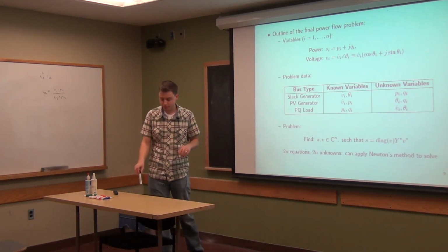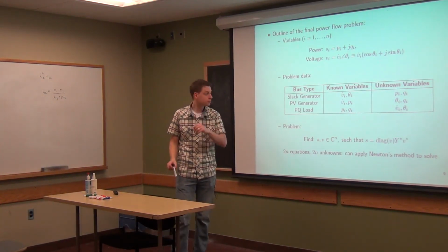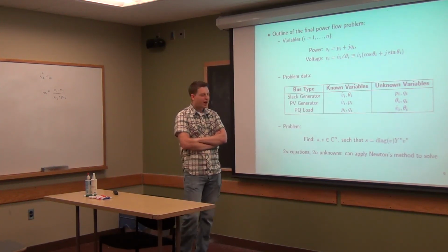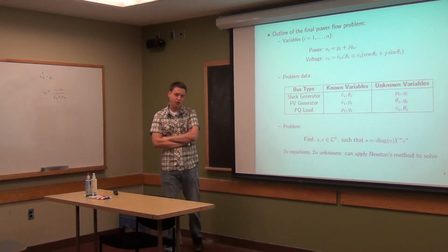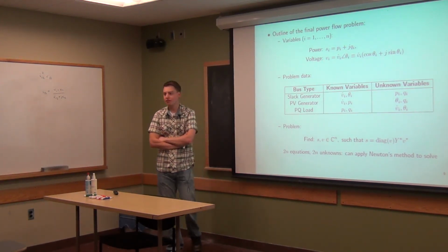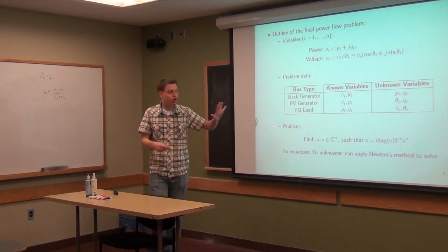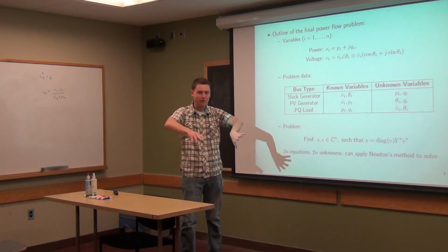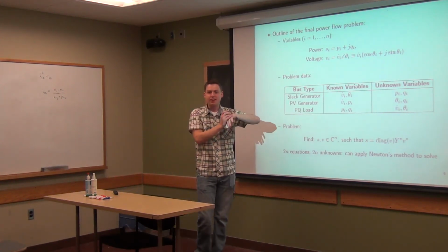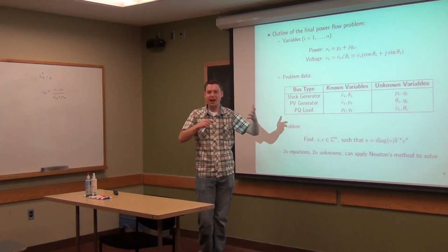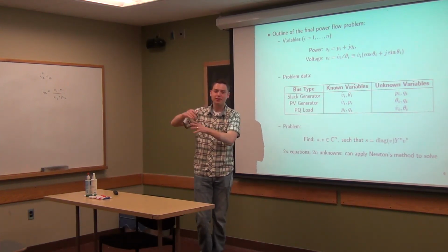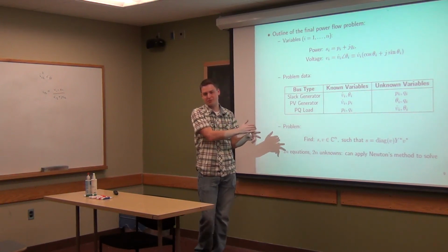So just to repeat, see if I understand, to actually solve for any particular network what was actually happening, you'd have to know the dynamics of how these control loops operate. If you really wanted to know, yes, you'd probably have to, because these are dynamical systems. Loads come on and turn off. This is all steady state analysis, right? So this is just saying, given some fixed load, this is what's going to happen. What would actually happen would depend on how those generators come up to provide that load. This gives you one steady state solution.